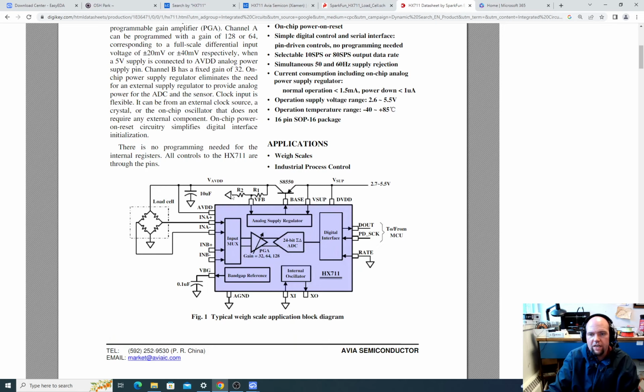But to do so, it needs a set of feedback resistors and a transistor, and this is exactly what we talked about with the linear regulator. The linear regulator just uses a transistor to burn off voltage. The way it knows what voltage it's producing is with a voltage divider. It's using a voltage divider to make this voltage smaller than what's actually here, and feeding back to a constant voltage.